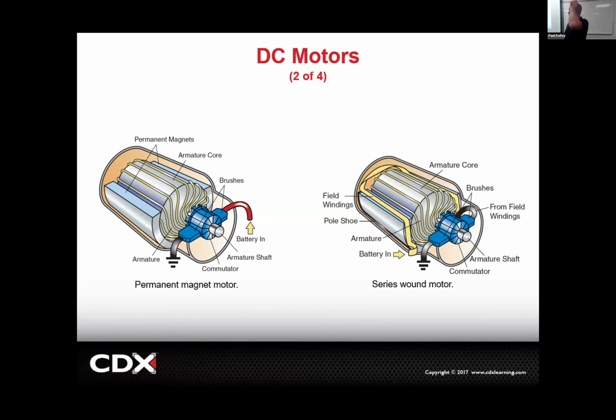So it sounds insane, but there is the way I was taught, which is if it's a bad motor, check for 12 volts, check for ground. If it's got 12 volts and ground and it doesn't work, it's a bad motor. We don't really care if it's the brushes or whatever.